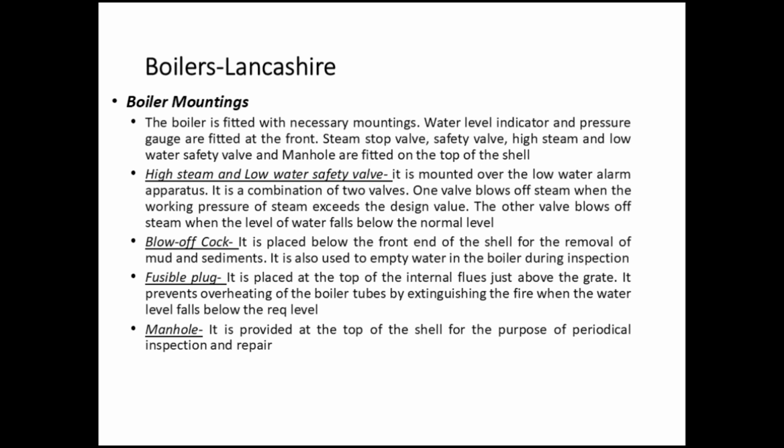Blow off cock. It is placed below the front end of the shell for the removal of mud and sediments. It is also used to empty water in the boiler during inspection. Fusible plug. It is placed on the top of the internal flues just above the grate. It prevents overheating of the boiler tubes by extinguishing the fire when the water level falls below the required level.